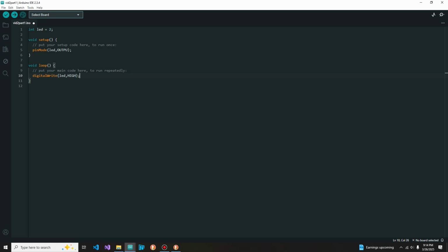And in the programming world, especially with microcontrollers, or Arduino specifically, HIGH means on. In this case, it'll be 100% on. There are 255 steps in between for dimming purposes for the Arduino Uno.